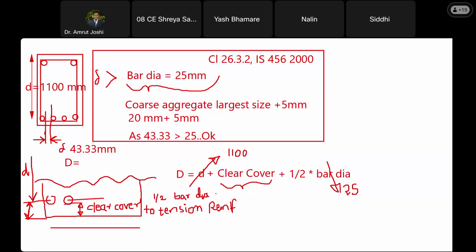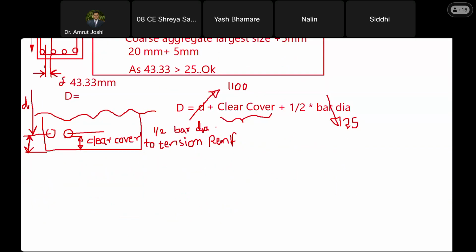So to make it neater for understanding, let me draw another zoomed in view. So you have these bars, 1, 2, 3, and 4. 4 bars. Below that, you are going to have a stirrup like this. And mind you, it is touching the bottom surfaces of all bars. Happy? Yes, sir. So stirrup will go like this.